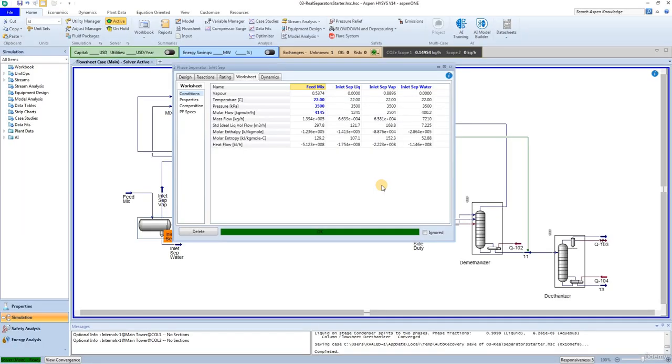Task 3. Adding a secondary separation device. While the separator studied in the previous task seems to work well enough, your heat exchanger designer could be a bit concerned. The LNG-100 exchanger brings in the outlet separator vapor stream as its hot side inlet. Based on your correlation-based real separator calculations, a significant flow of liquid droplets will feed into the exchanger.